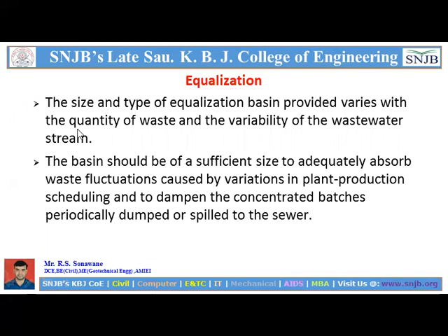The basin should be of sufficient size to adequately absorb waste fluctuation caused by variation in the plant production, settling, and dampen the concentrated batches periodically dumped or spilled to the sewer.